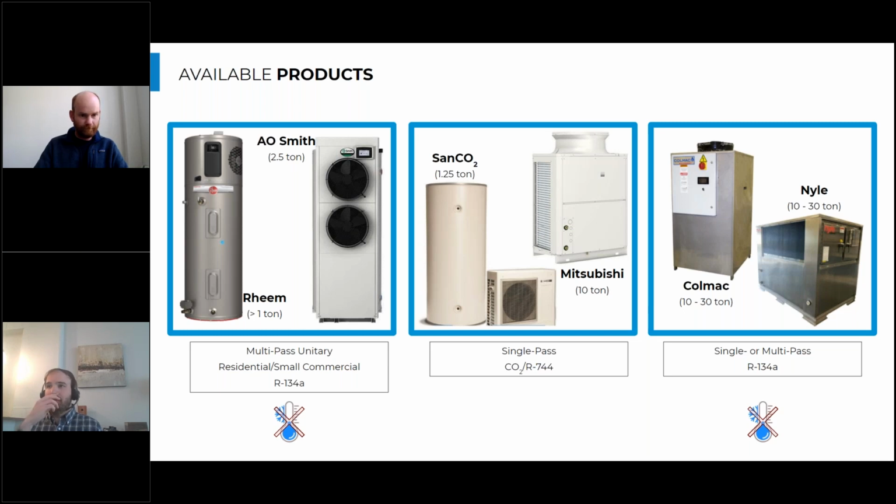Perfect. And so yeah, on that too, someone's asking, are these commercial heat pump water heaters typically rated in terms of tons, and is this the tonnage of the cooling side? So this is a great question. Typically we talk a lot about tonnage specifically for cooling, but tonnage is 12,000 BTUs per hour. A little bit easier to say than 12,000 BTUs per hour, 1 ton. So that's why I'm using it here, but this is the heating capacity for all these.